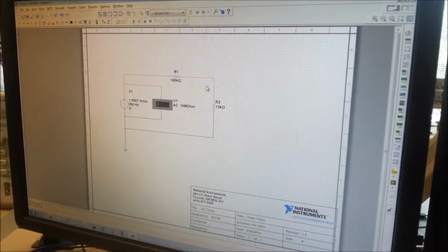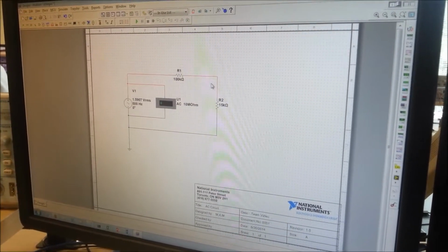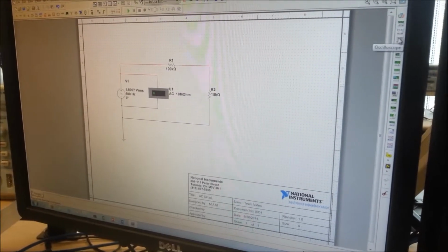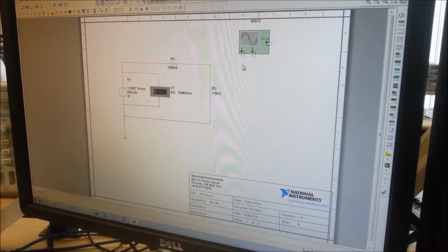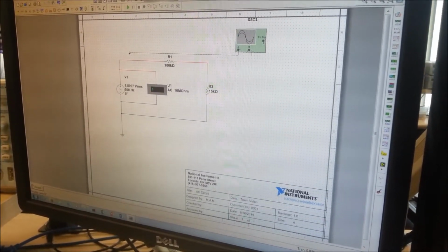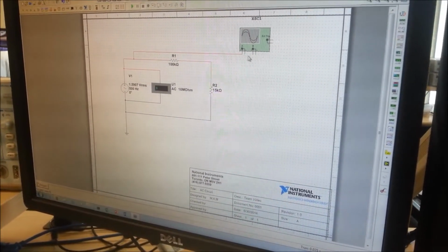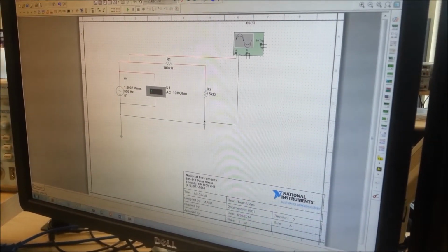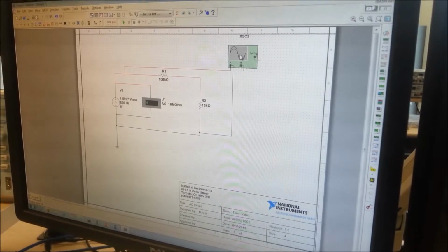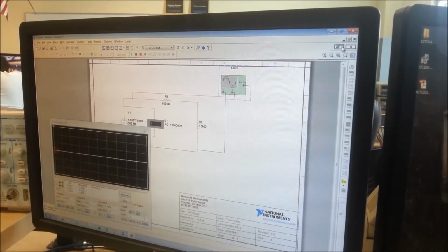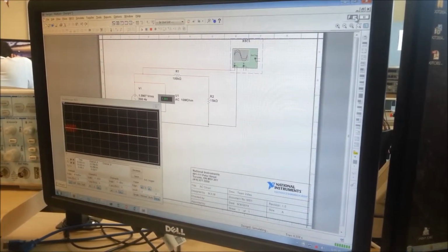Michael, I'm going to show you how to measure voltage peak to peak. First, we're going to choose our oscilloscope. We're going to connect it to our circuit that we've already built, ensuring that we include all of our resistors. And we're going to begin our measurement. Turn our simulation on. Get our data.